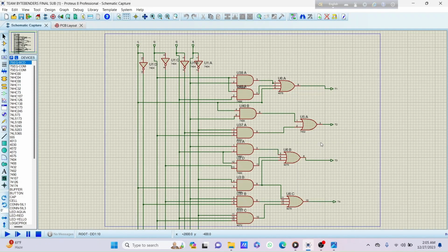Now how does the double dabble method work? The double dabble method shifts each binary digit at a time, simultaneously checking if the binary number is greater than 4 or not. If the binary number is greater than 4, then this circuit adds 3 to the number and repeatedly shifts the number until the binary number is converted to BCD representation.